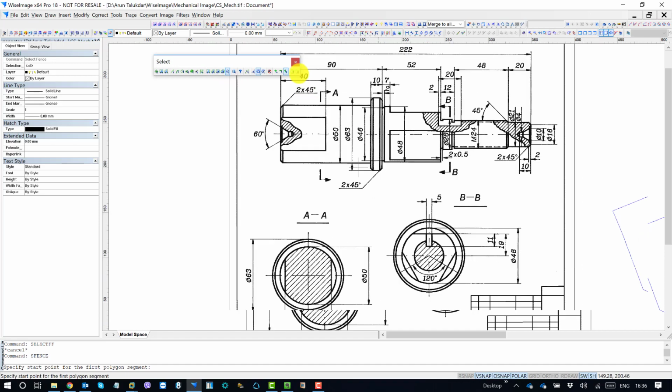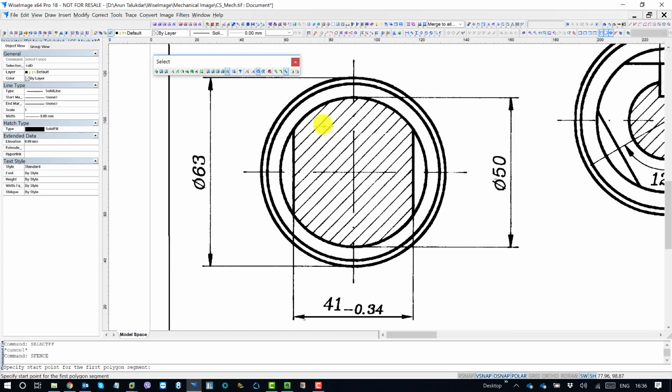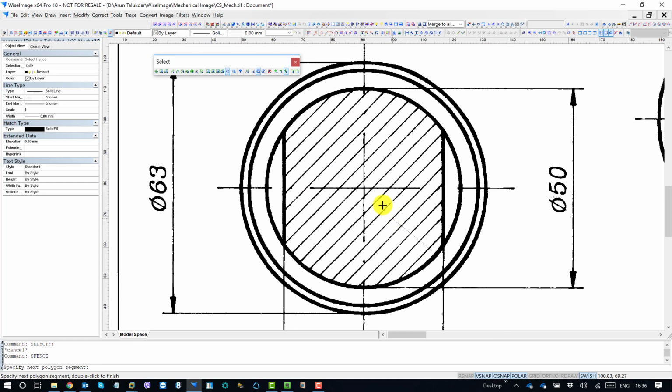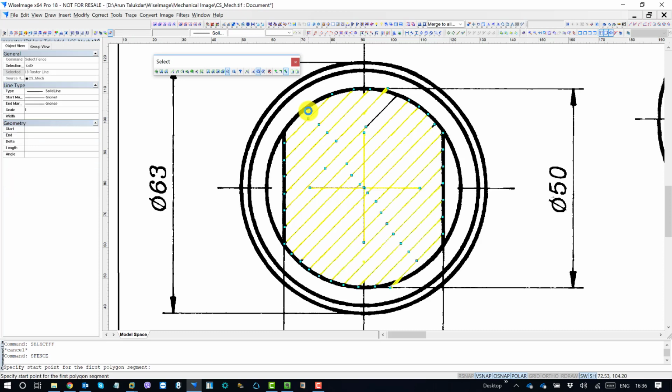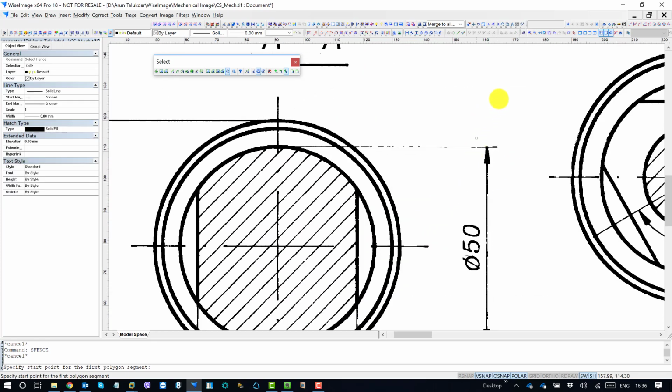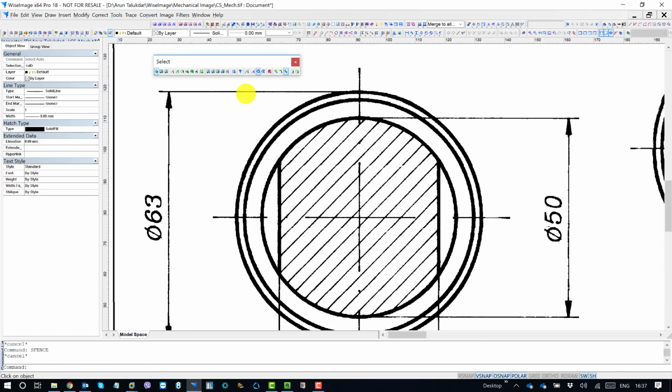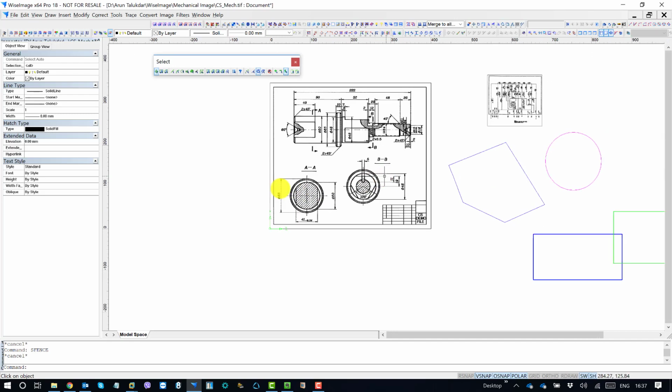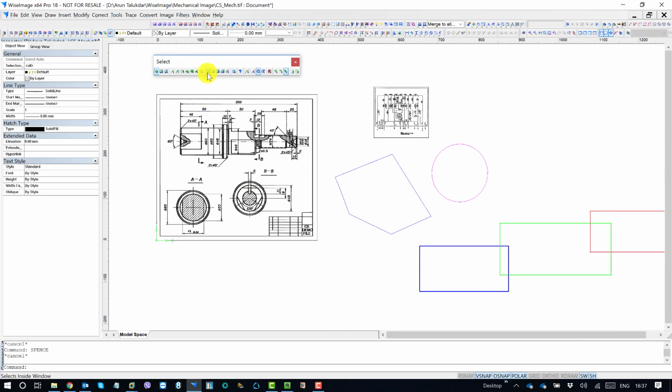These are a few tools for your use. This is one function that we use to select raster hatches. In this case I need to point at the hatches like this, and when I end, I double click, and it will select all the raster hatches. So this is also very useful. The cursor shape will be something like this. Double click will remove the tool like this. So going back again to auto, these are some useful tools as well.